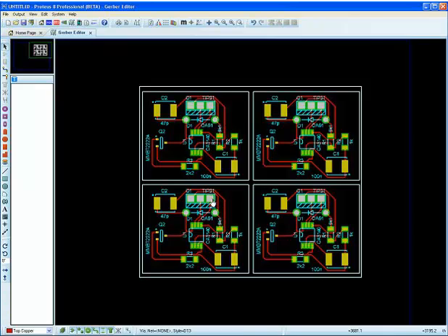You cannot panelize a board while the project is open. A Proteus project is a representation of a single board: schematic, layout, 3D visualization, bill of materials, etc. And a panel is clearly a representation of more than one board. Make sure you close the current project before you enter the Gerber viewer in order to panelize a board.